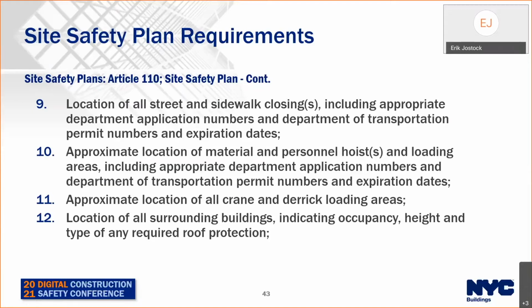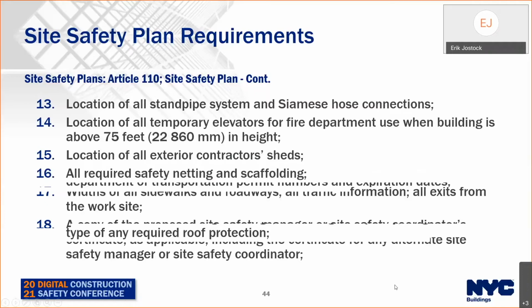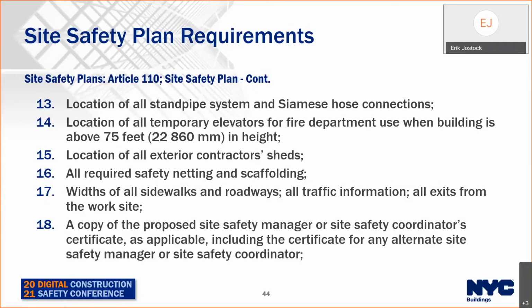Approximate location of all material and personnel hoists. Approximate location of all crane and derrick loading areas. Location of all surrounding buildings indicate occupancy, height, and types of required roof protection. Location of all standpipe systems and Siamese hose connections. Location of all temporary elevators for fire department use when the building is above 75 feet in height.